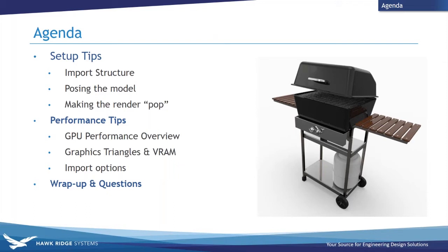At first we'll be focusing on the import settings, streamlining your workflow, and quite a few things you can do in SolidWorks to make your life easier in Visualize once you get to the actual render. And then also some background on how Visualize works, the graphics card hardware that it can run on, and things to reduce the burden on those graphics cards. So that's the way we have it structured here. Hopefully it'll be helpful for everybody.